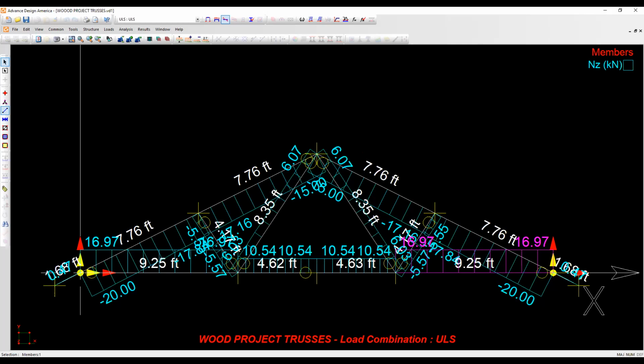So what you have to keep in mind is that if you guys think you need to get exactly the same results that I do, I try to be precise, but I also look at MR is 10, MF is 7. Wow. So even if my analysis is slightly off, I know I have a lot of resistance, so if I've underestimated something, I have some margin before my MF gets close to my MR. That's what I want you guys to appreciate.